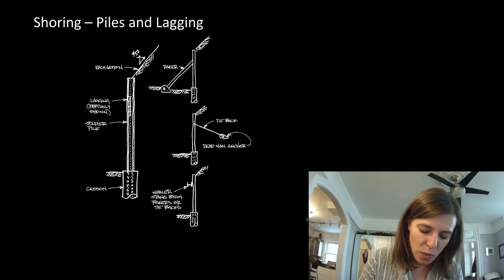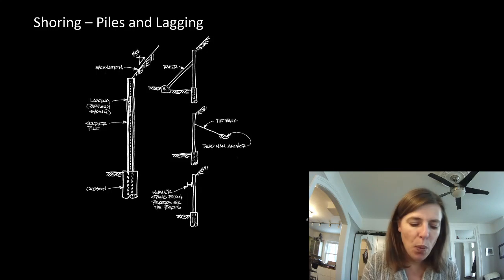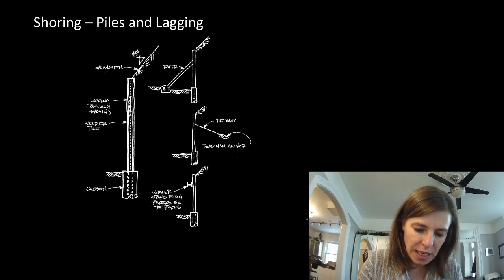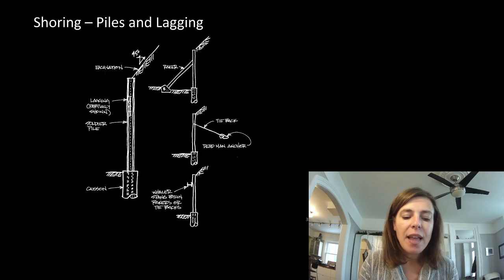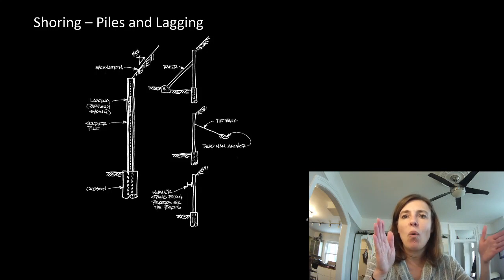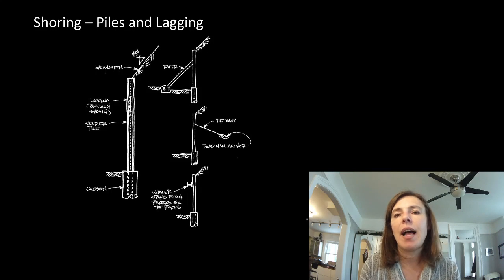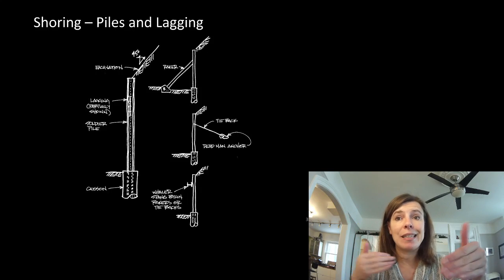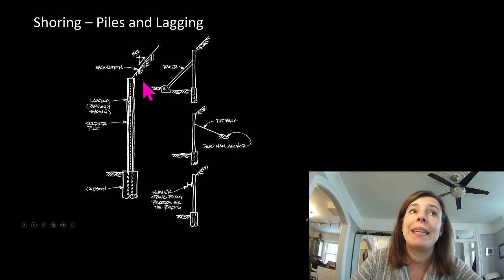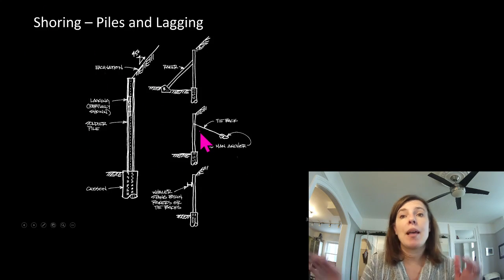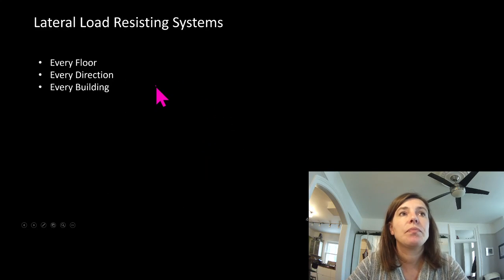8 minus 1.2 leaves a 6.8. That means we'd need to excavate away from the site almost 10 meters, which, you know, in major cities, you're pretty tight to the property line. So that's where you might need shoring to be able to do your construction.